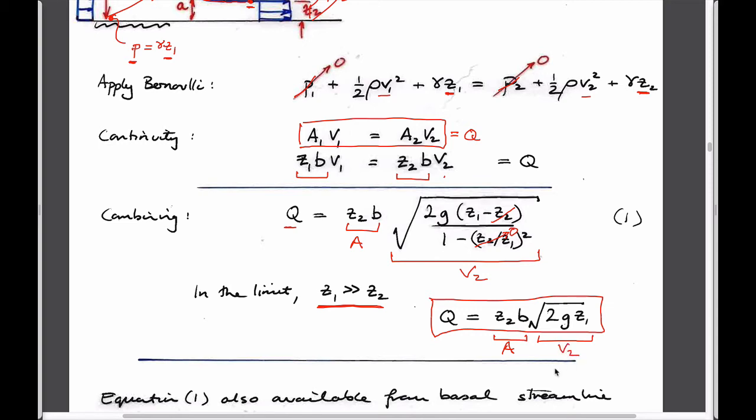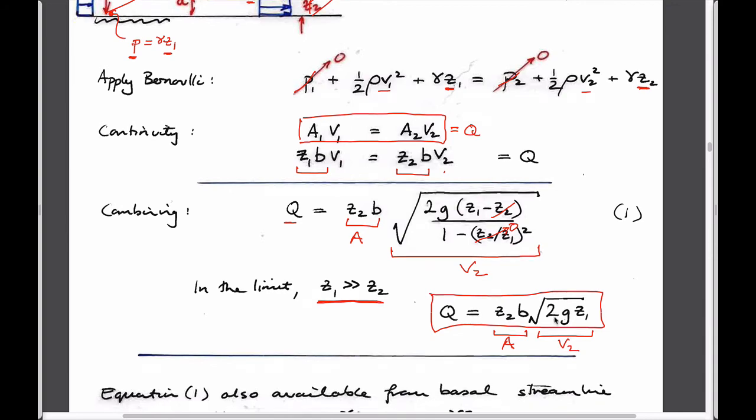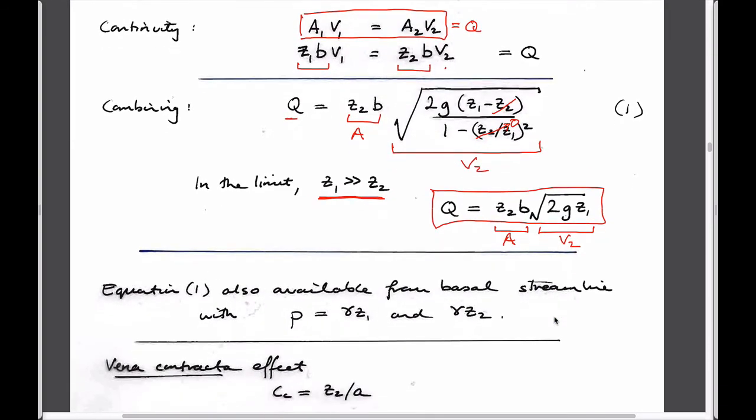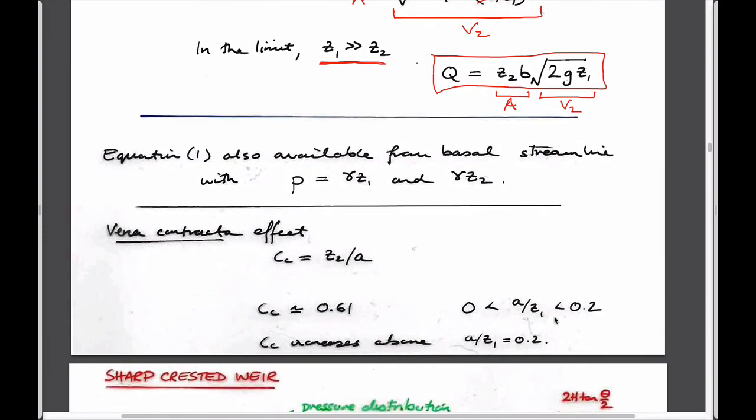So it's almost the same as having a bucket of water with a hole in the bucket. The height of the water in the bucket relative to the center of that nozzle gives you a flow velocity out of the system, and it turns out to be roughly the same. Not surprising, it's roughly the same expression here. This is the equation of water being pushed out where there's no pressure added to it to be able to push it out. And so maybe it's not surprising.